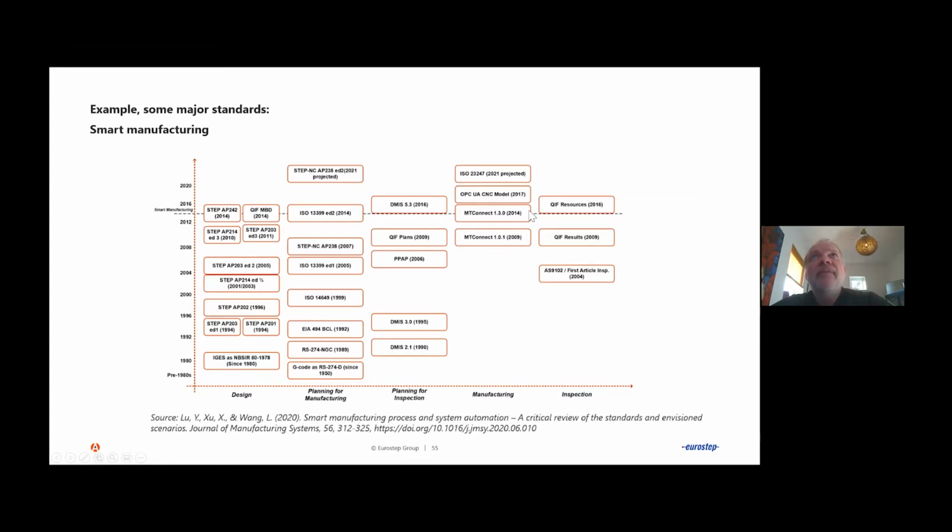For example, within metrology and inspection, there is this QIF, which is standards that today have been incorporated into the ISO 184 subcommittee 4. So those standards have been incorporated there and will become ISO standards as well, but they emerge from American industry. But for one example, they also have a lot about geometry definitions in there. So that's an example where we have geometry information in the QIF standard, we have geometry definitions that is within the STEP standards, which are overlapping but a bit different.